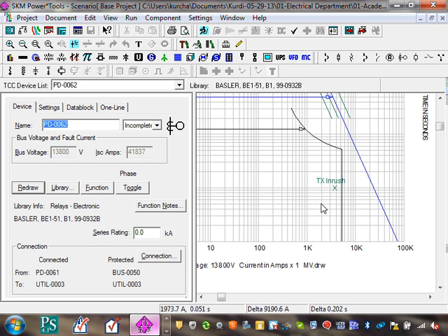So when you set your relays, I put number 6 here. When I set my relay, I put my conductor. I can tell by putting my relay here that my relay cannot protect this conductor. So I have two options: either I lower the setting of my relay or increase the size of my conductor. If I lower the setting of my relay, well, Chad, how about if you put it too low here? So see what happened? If you put it too low, this is the inrush of the transformer, that's protecting the transformer primary. If you put it right here, every time you energize the transformer, bang, it opens. Is that what you want? So you have to clear that little point.